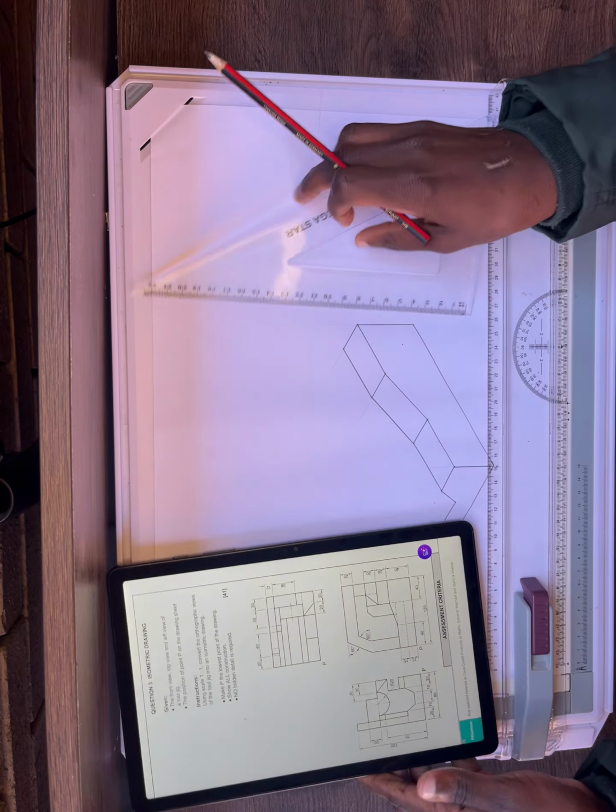Right. But do you think I should make this piece dark? I cannot make it dark yet, because remember, this line that I just drew here, it represents which one? It's representing this one. Alright, so I cannot make the piece dark right away, because I still have to draw a line that comes this way, which tells us that some of the pieces are going to be hidden.